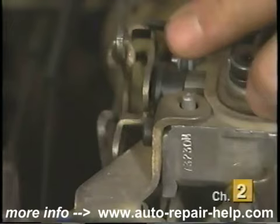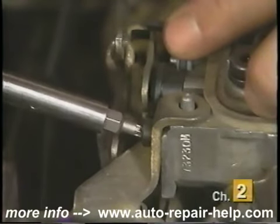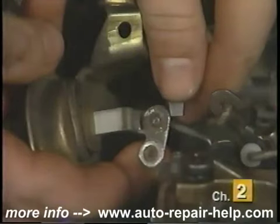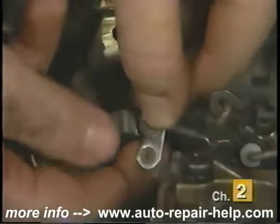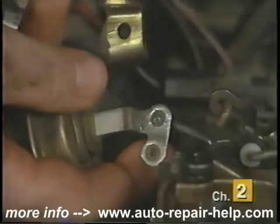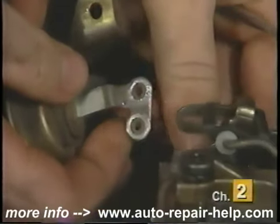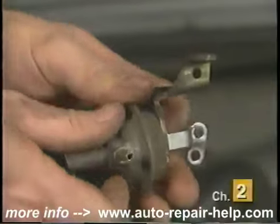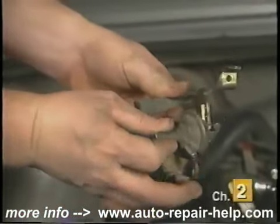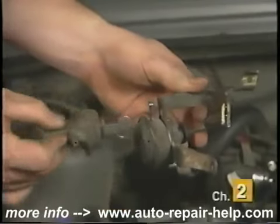Next, remove the mounting screws from the old pull-off. This is when the magnetic screwdriver comes in handy. Carefully remove the pull-off while disconnecting it from the linkage. Take your time so as not to disturb or bend any linkages during removal. Many choke pull-offs have a bracket that must be transferred to the new part. Remove the pull-off from the bracket if so equipped.